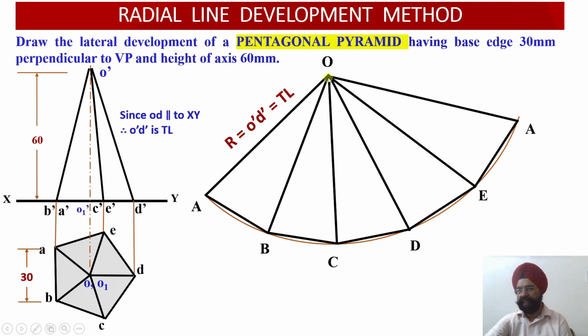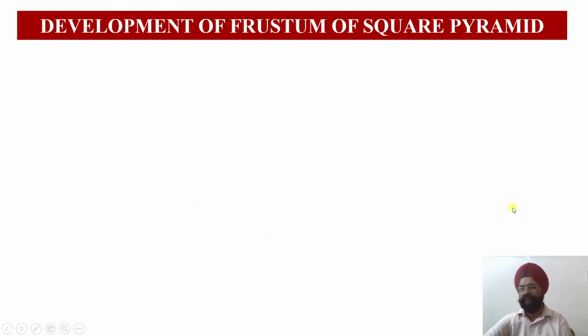So here I have a center, and then this arc is only there for the construction. This is not the part of the development. So the straight edges will be the part of my development because the base is straight. So had it been a cone, I would have used the outer circle or arc over there.